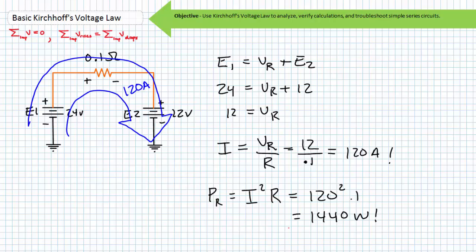What this goes to show is that a fundamental understanding of KVL illustrates that voltage sources of different magnitudes in parallel are to be avoided at all costs. The only time voltage sources are ever placed in parallel is if they are the exact same magnitude. Any differential will cause the larger voltage source to discharge into the smaller source until the differential between them is exhausted, potentially with damaging results and an extremely high current flow.